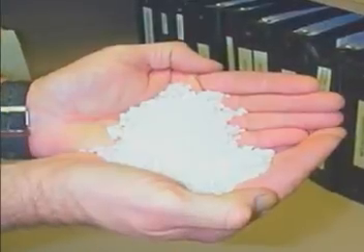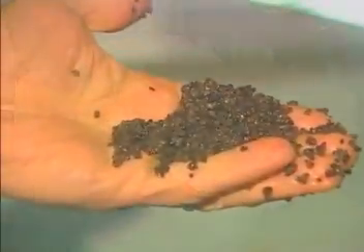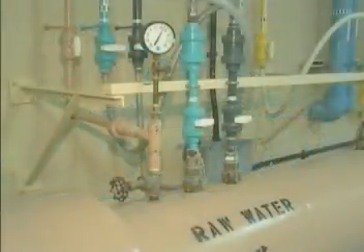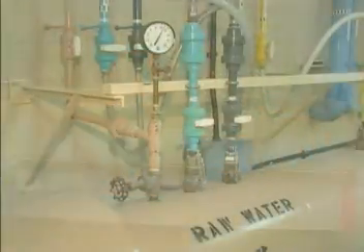In the upflow clarifier portion, differing types of media are used to trap most of the unwanted matter. The media types include plastic beads, sand, and garnet. In this process, the coagulant chemical is added before the clarifier. The clarifier portion is cleaned by backwashing or flushing with untreated water.